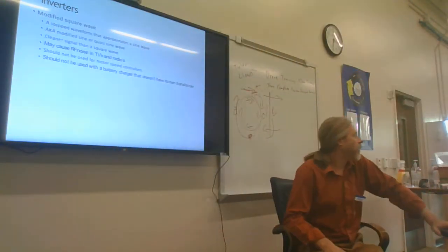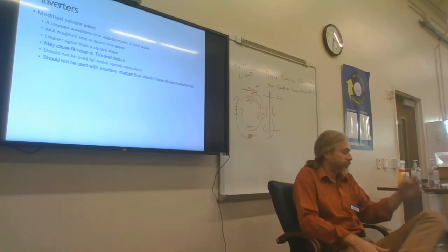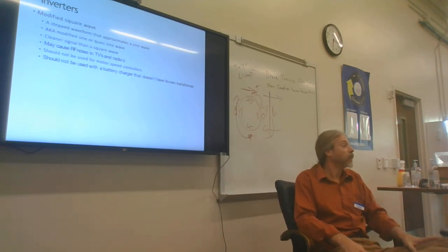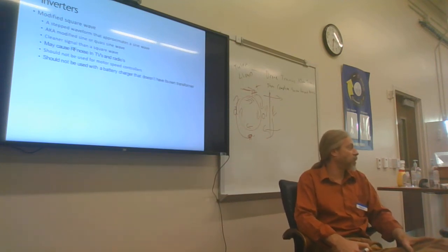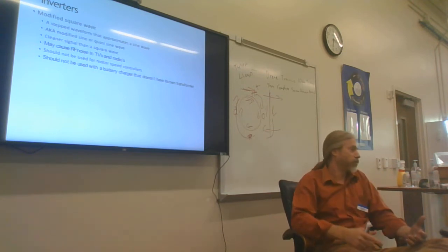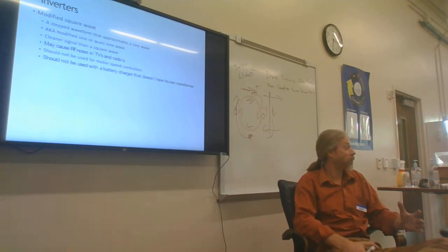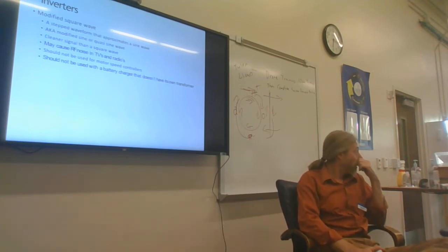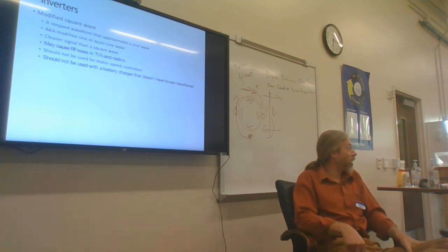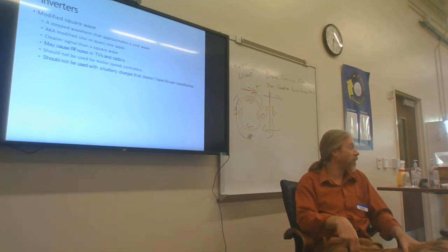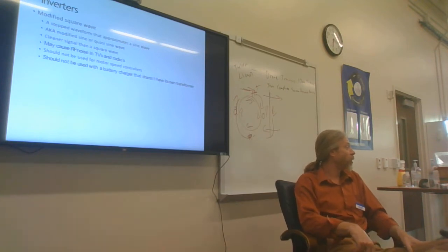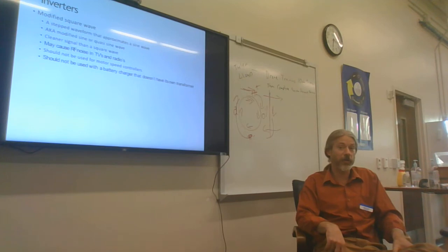Okay. The term quasi sine wave, I don't like. It's misleading, but it is still fairly effective. Anything that would be listed as a modified sine wave or a quasi sine wave would be approved to run induction motors. Though you're not going to burn them up, not going to be quite as efficient. They have a clearer signal than a square wave, but still, even modifieds can cause RF noise in TVs and radios. They should not be used for motor speed controllers. They should not be used with a battery charger if it doesn't have its own internal transformer inside.